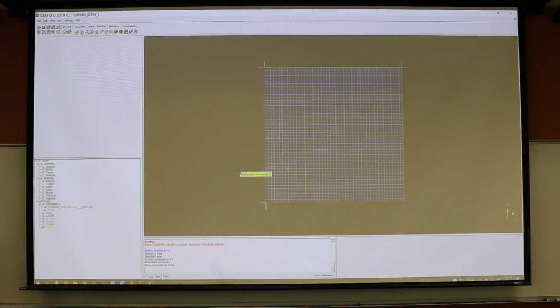That block, if you are trying to mesh a circle, you will find that this vertex, once projected to that circle, will look something like that. It will be a very squeezed element. In reality, if you do this by yourself, you will get that type of mesh. That point here, and then you will get 2 points there, and you will get 2 points here, and 2 points here, and that's it.